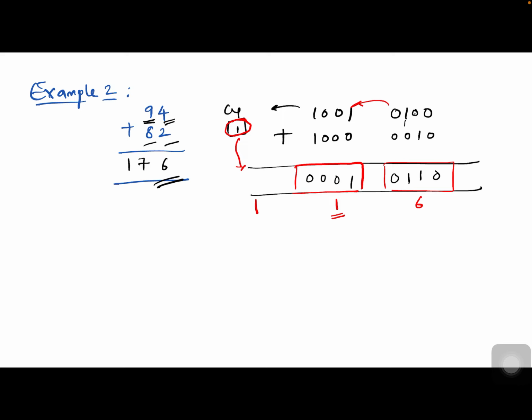So before I go for DAA instruction, what I just wanted you to know is that the result that we have received is 116, and the actual result should be 176. Since it is not matching, obviously it will not match, because you were anticipating that 94 and 82 are decimal numbers. So basically 176 is 176 to the base 10. But let me tell you, microprocessor is going to make believe that whatever numbers you fed to microprocessor for operations, they are going to treat that as a hexadecimal number, and that's the reason why you got result as 116.